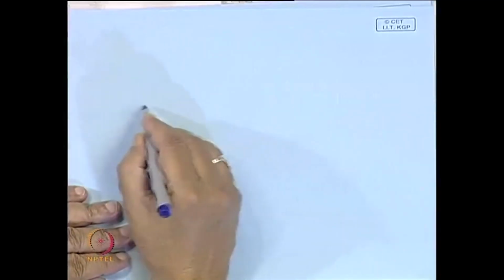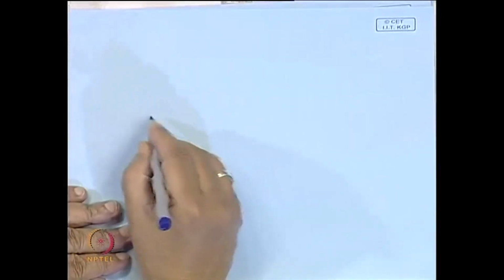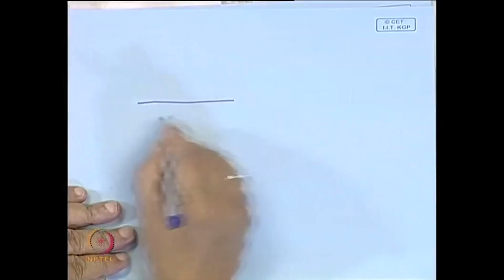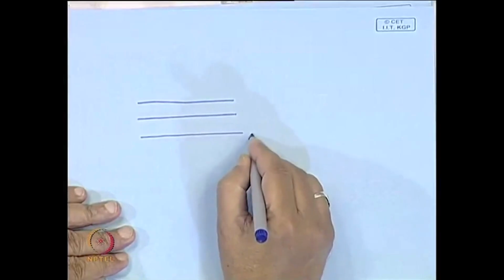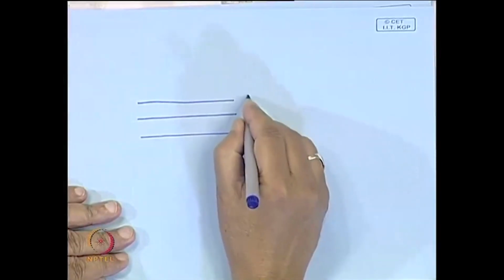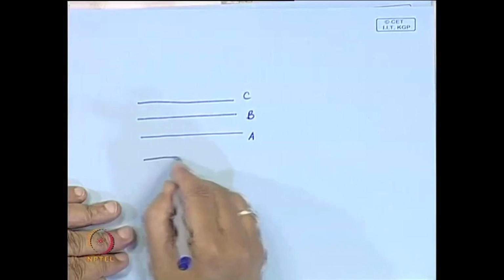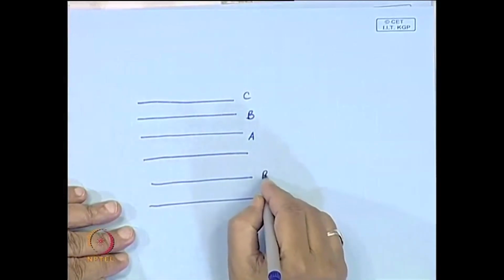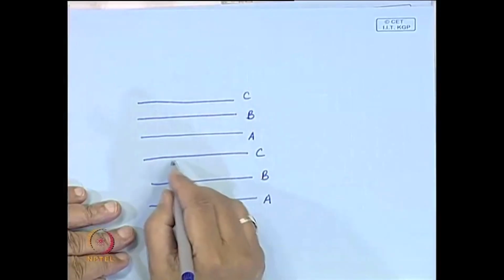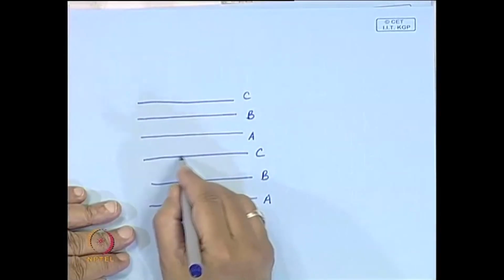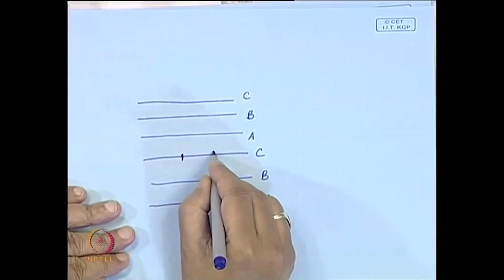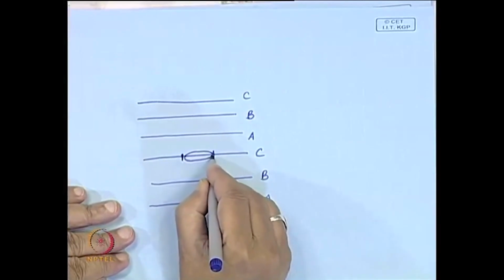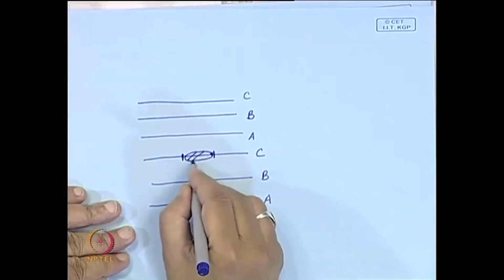We know that the layers in face centered cubic crystals, this 1 1 1 plane, are arranged in this sequence A, B, C, A, B, C. Now, what is happening here? These vacancies are concentrating over here. So this area, these vacancies have come here and this goes out.